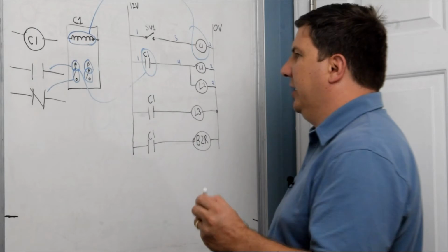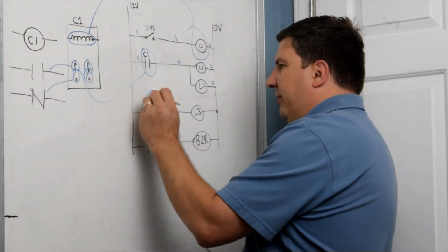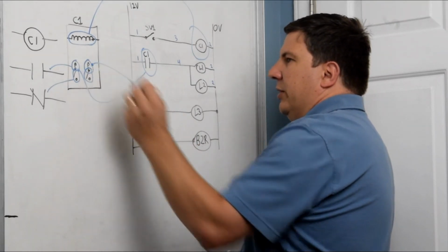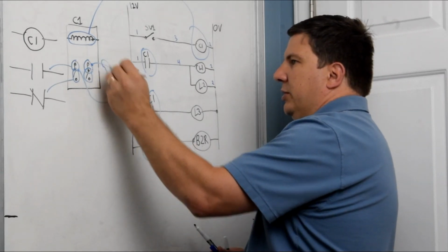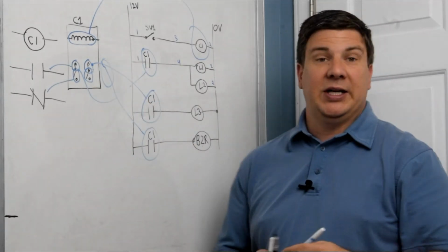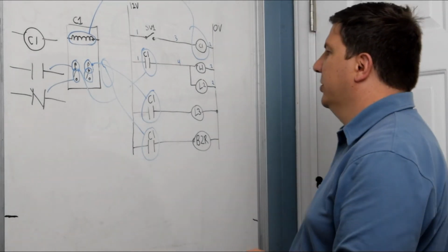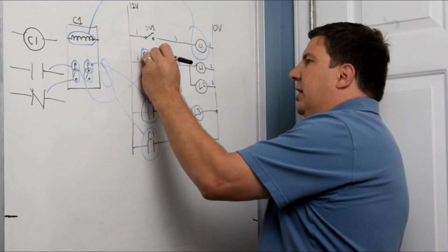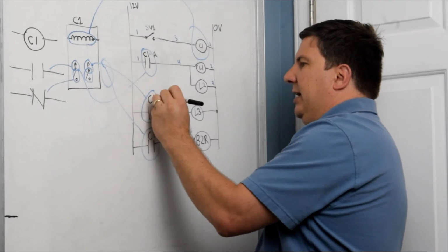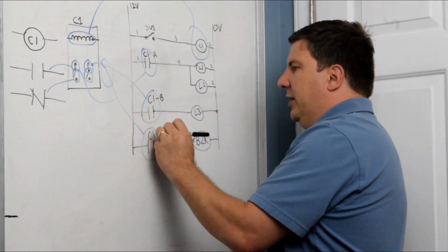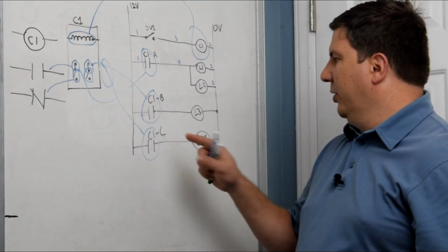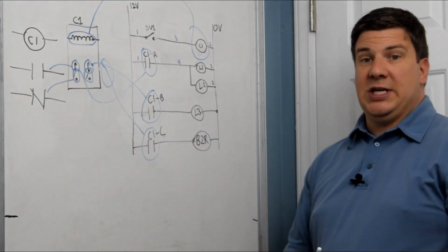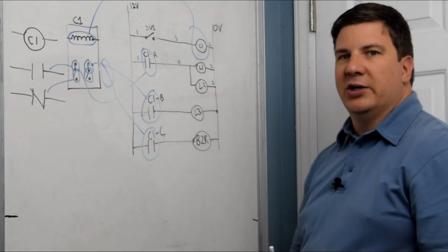So you can see here that I have readily available this one right here, but what I don't have is one for this one. So I would need to get a bigger contact. And occasionally you'll label these like this is going to be contact set A, this will be contact set B, and contact set C. So if you can go through and you see a C, you're like, ooh, I need to get a special relay for that.